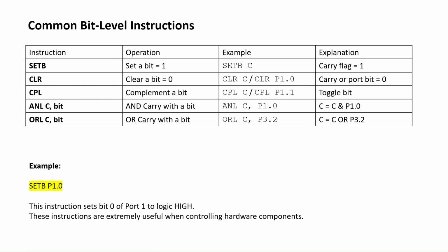CPL, complement bit operation, toggles or inverts the bit value. Example, CPL C. If carry equals 0, it becomes 1. If carry equals 1, it becomes 0.